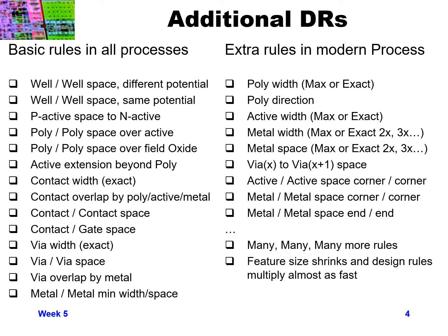With metal widths, you might run into something where you can have, again, a maximum metal width. Let's say you can have your minimum metal width, and then maybe at maximum you can go up to 3x width or 4x width, but you might not be able to go more than that. And in some cases, the same thing for metal space. You might have a minimum space, but then also a maximum space between neighboring metals. Similar thing for vias.